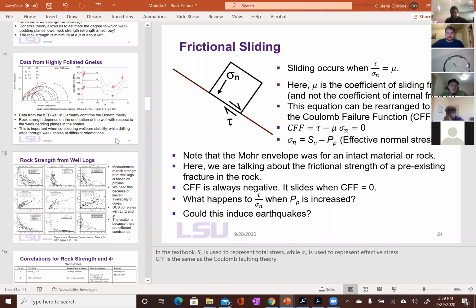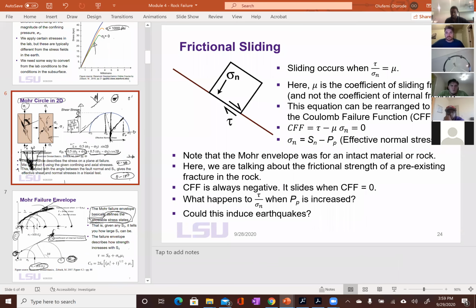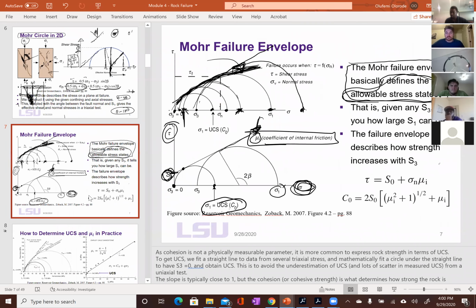So instead of going too deep into that, I'll give you the bigger perspective so you can see the big picture right now while we're here. You notice we are talking about rock strength, right? And all we've talked about is the compressive strength of the rock, the strength of the rock under compression. There is also the tensile strength of the rock, the strength of the rock in tension, different from compressive rock strength.